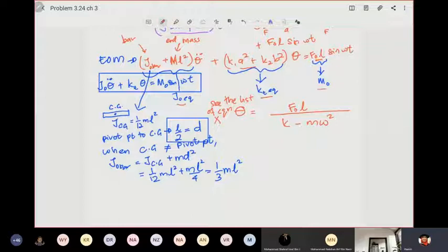So what do we have then? What is your K? What is your M? What is your omega? Your K is K torsional, K equivalent, which is K1 A squared plus K2 B squared. So that would be your K. Then your M is not just M. A lot of students make this mistake. So your M will be the whole thing.